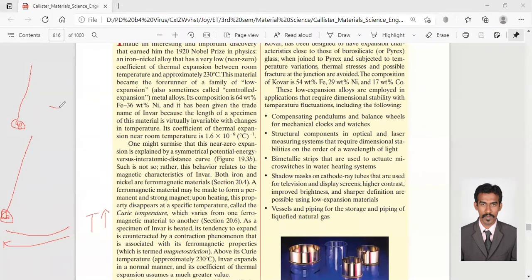So a bimetallic strip is a structure of two metals, right? These are usually used in an iron box. One can be aluminium, and say for example the other is Fe. If the thermal coefficient of aluminium is high, this will expand fast. So when you increase the temperature, aluminium would extend up to here, and maybe the iron can go only up to here, right?